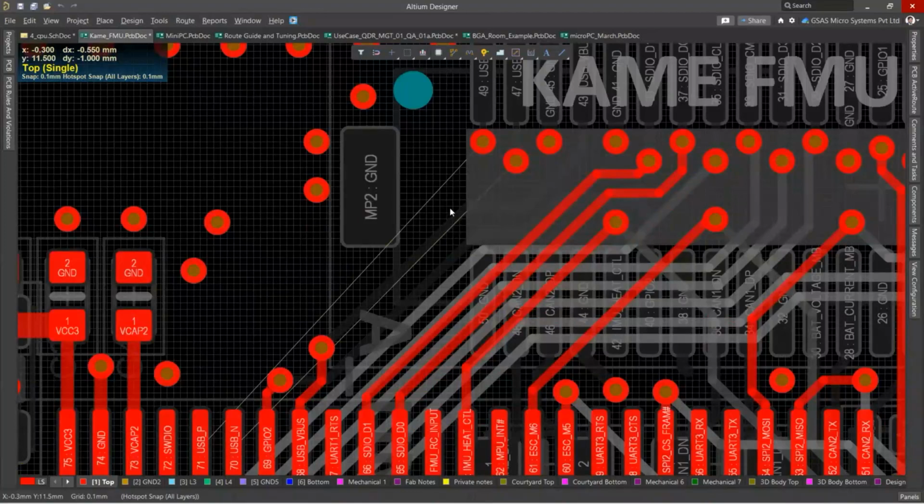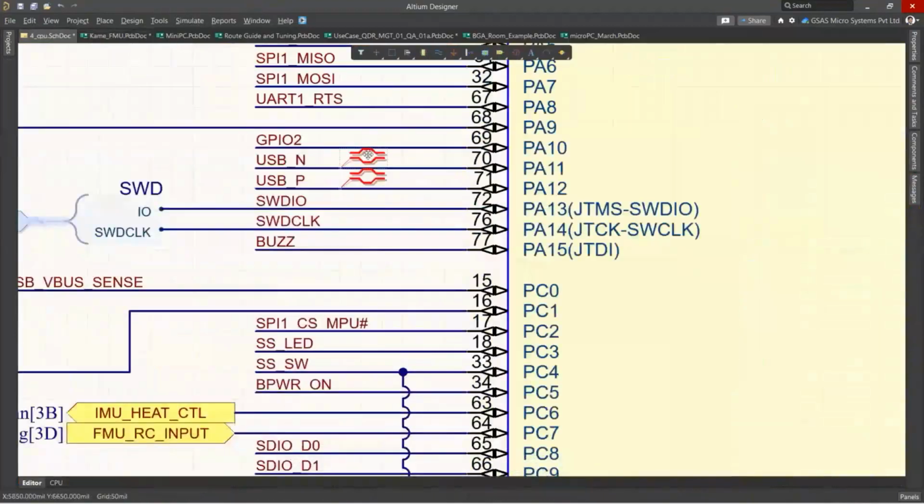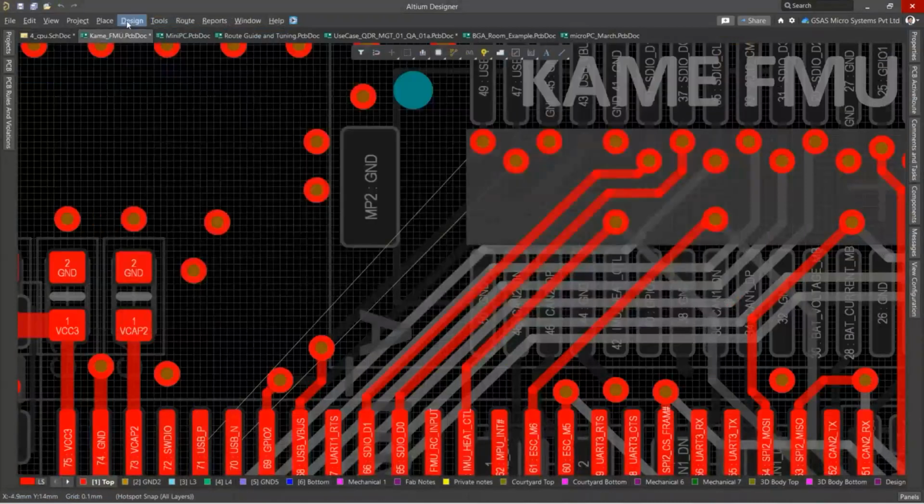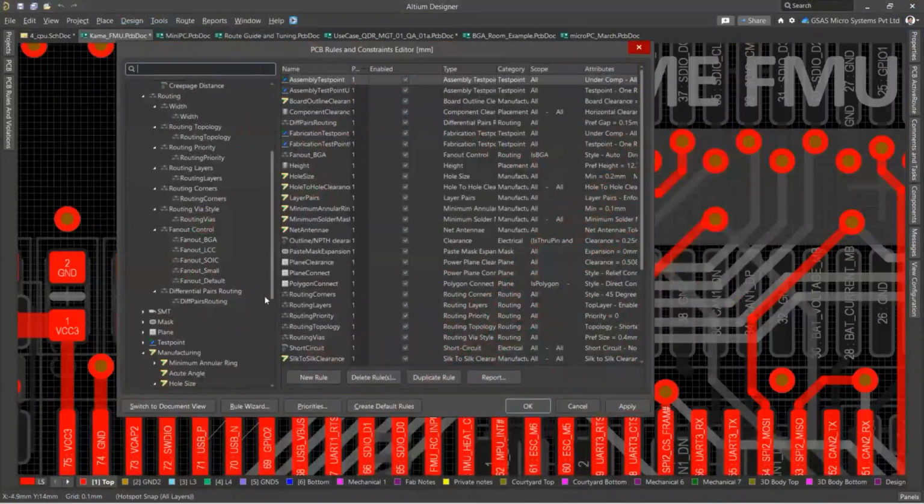can push this design back into Altium Designer with a single click. Now let us see how we can define the differential pairs in the PCB editor if they are not defined in the schematic. For this, let us undo the changes. Let us remove this and update, and it will remove those things. And if you have a look, yes, we have removed everything.